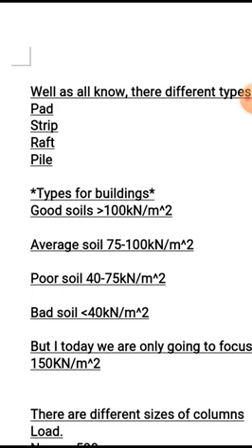In cases where you have a good soil, mostly we use pad foundations and strip foundations. And in cases where you have bad soils and poor soils, most times we use pile or even raft foundations. It's common in the islands in Lagos, where you see a lot of pile foundations and raft foundations.